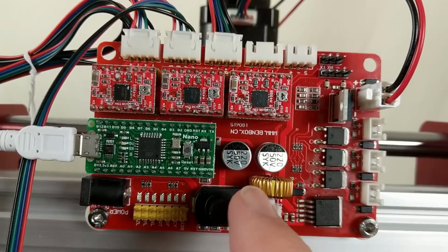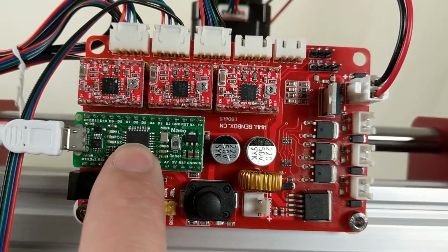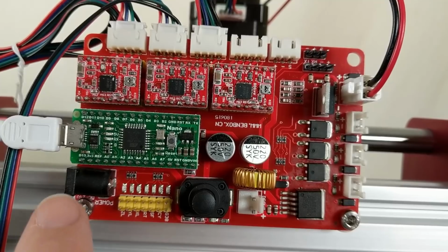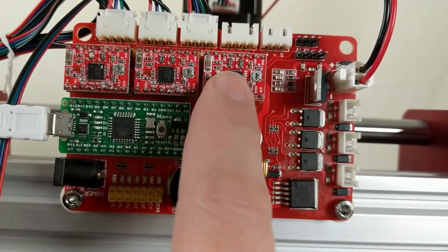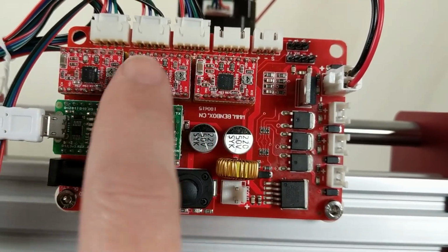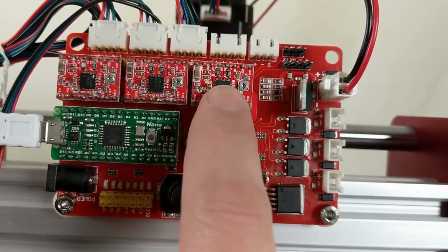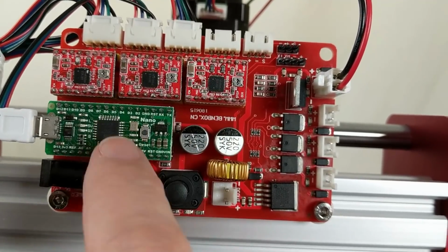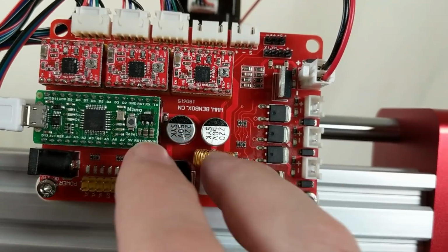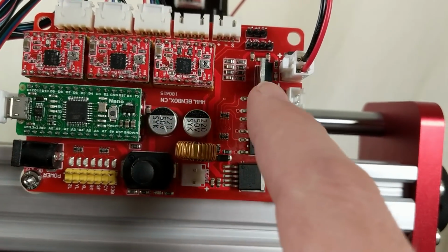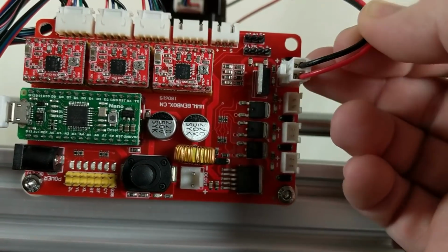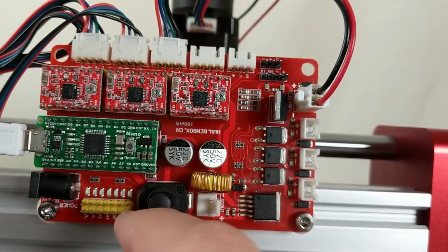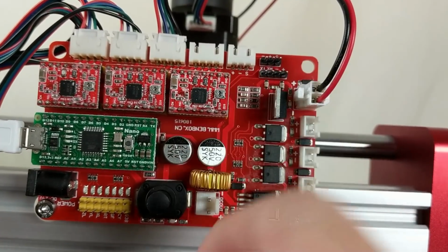Let's take a quick minute to talk about the control board on this little CNC machine. So that is a Chinese clone of an Arduino Nano, as you can see right there. This is the on-off switch, push button on-off switch. There's the power jack. These are 3 Pololu A4988 stepper motor drivers, obviously Chinese clones on those. So these are going to be terrible for the micro-stepping. They are not very fine resolution, and also they're very noisy. But we don't really care about that kind of thing when we're going to be making all kinds of noise cutting through things. So those are going to be the quietest part of the machine. This here is the power and ground signal that are going to the spindle motor, and this is the MOSFET that hopefully will give us pulse width modulation, so spindle speed control.